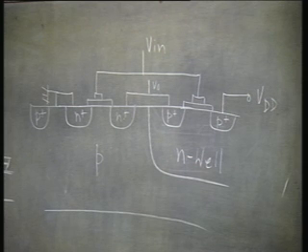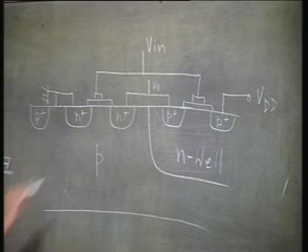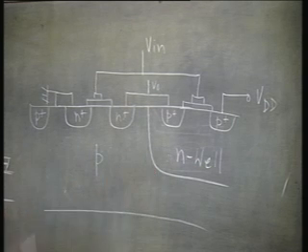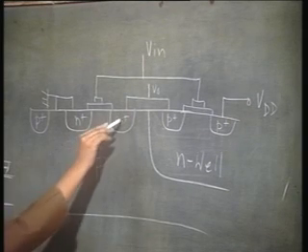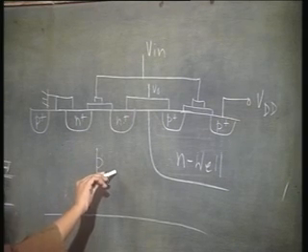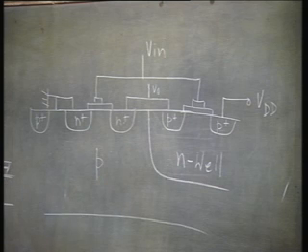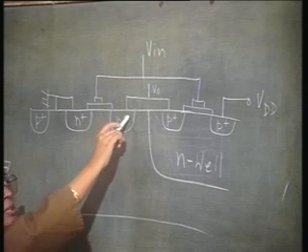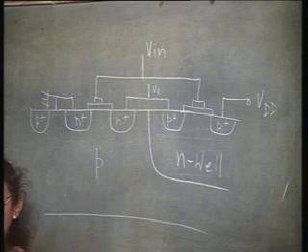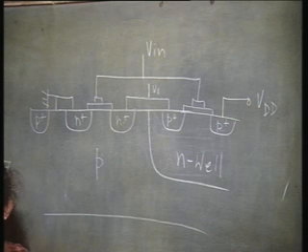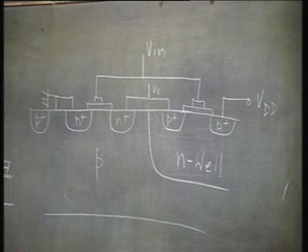Now, what will happen? These electrons can enter this NPN transistor, you are injecting electrons here. It is an NPN transistor, you have forward biased the base emitter junction, so it starts conducting.